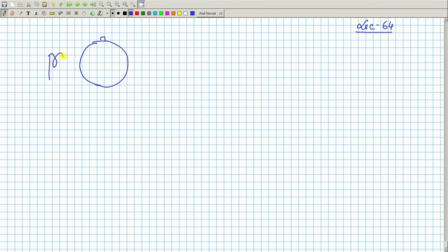which is represented like this here, and this is the flux per pole created by the machine when you pass some current I F here, and we considered generator mode of operation, and suppose it was running in this direction with a speed n, then this side is north pole, this side is south pole.